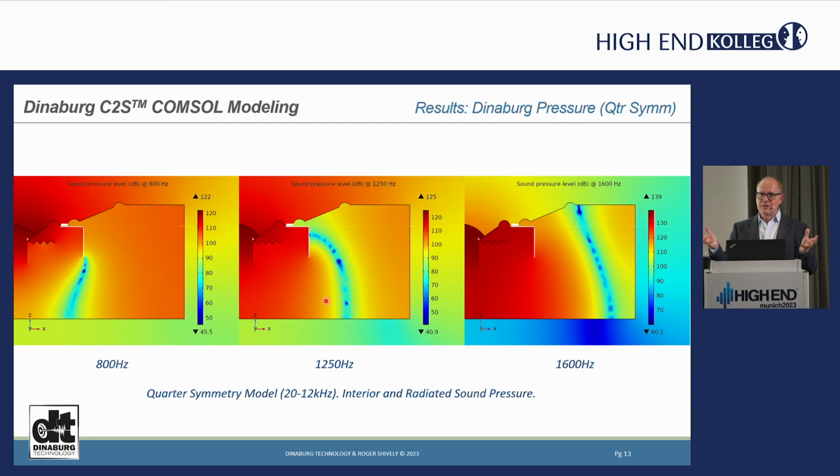And then we just started to scale it down to something that could be using a 6-inch mounting with a 3-inch center. And then it was a question of finding how slim could you make the box. And it came out to be 2.64 liters based on the depth. And that was where we started having too much interference and poor behavior with the back wall.